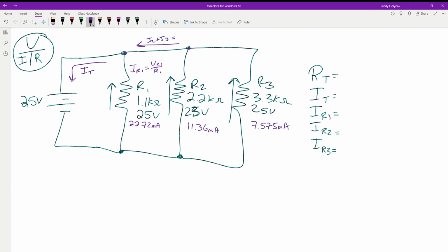And that is how much? Okay. And the reason that we know that this section up here coming out of this node is flowing this direction is because look at your inputs and your outputs. We have 3 connections. 2 of them are going in, which means we have to have current going out. So we get the 18.935 milliamps.